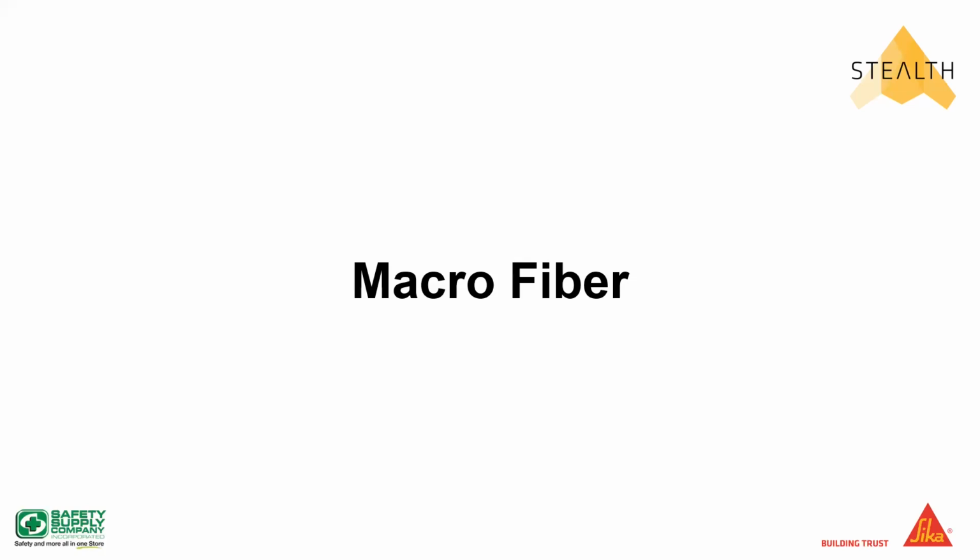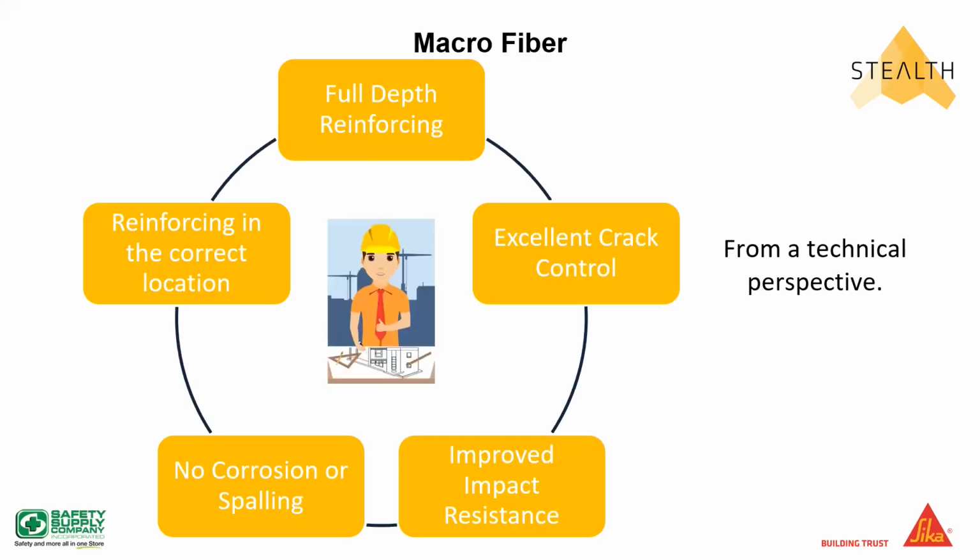However, if we do that, we are doing it with a macro fiber. And if you remember the types of fibers that I told you about with your macro fiber, you have steel fiber, you have the synthetics, and then you have what I mentioned, though I didn't show you a picture, the blended fiber. So from a technical perspective, in other words, from the engineer's perspective, what does it do? Well, it provides for excellent crack control, like the